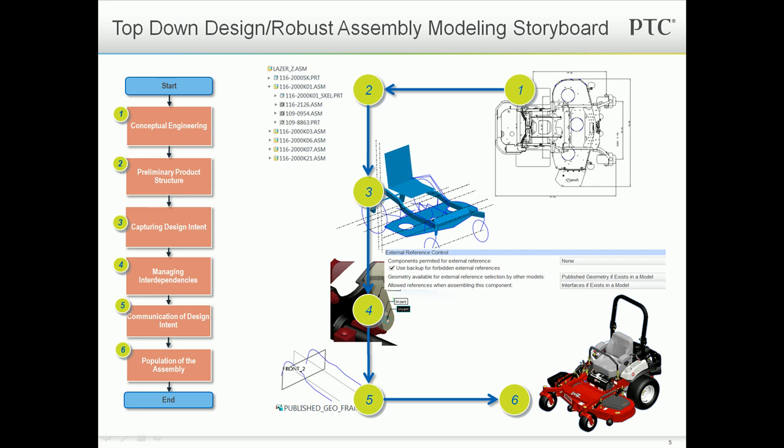The top assembly designer can easily distribute design task and intent to individual groups by using Creo Parametric's skeleton modeling to copy and distribute geometry functions. It will ensure the efficiency and quality as well as reduce the design complexity. After all the 5 stages are completed, we will go to the 6th stage, which is the assembly stage.